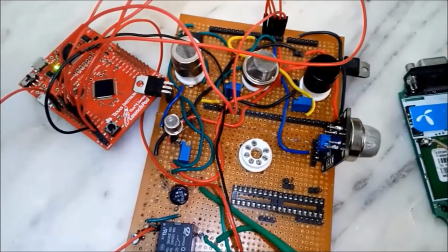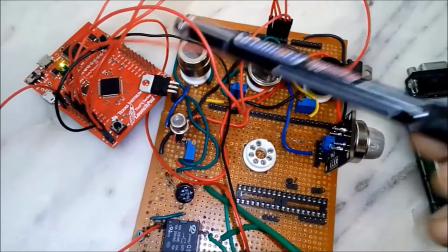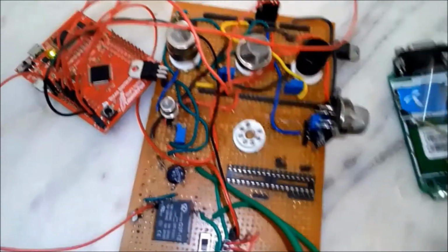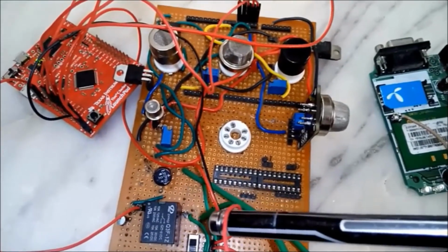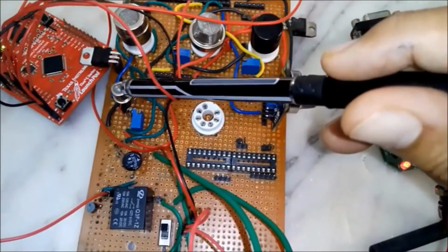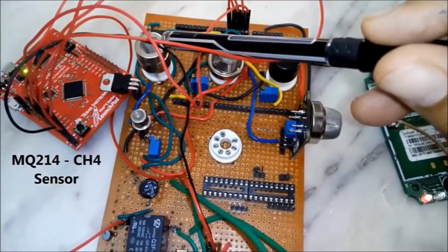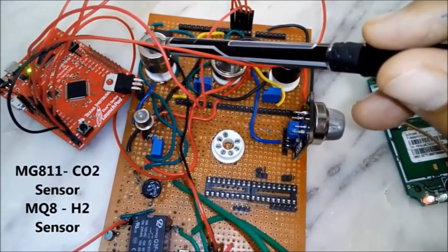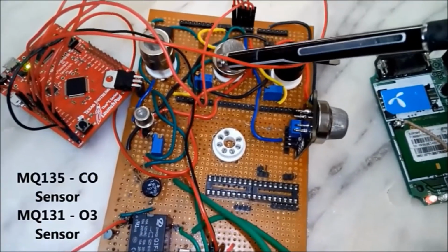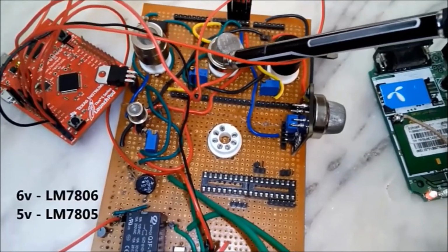Now we will look at the gas sensor modules in detail. Since a large amount of current is drawn by these gas sensors, we can't read them continuously. Hence we have designed a relay-driven circuit for driving the gas sensors. MQ214, that is the methane gas sensor, and the MG811 carbon dioxide gas sensor require 6 volts of heating voltage, while the other three sensors, hydrogen, ozone, and carbon monoxide gas sensors, require 5 volts of heating voltage.